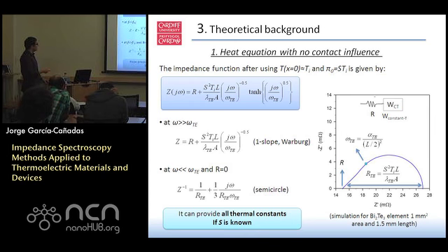And at very low frequencies, when the frequencies are much lower than this characteristic frequency, I have this approach, this simplification, and this provides the semicircle. So if we look, we can fit this response into an equivalent circuit, which is a series resistor with a Warburg element. The Warburg is an element widely used in electrochemistry, and it's quite frequently involved in diffusion.